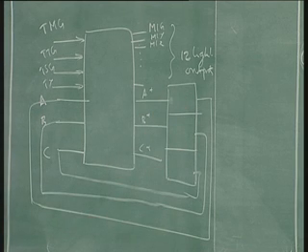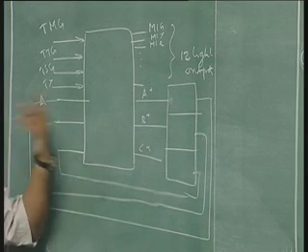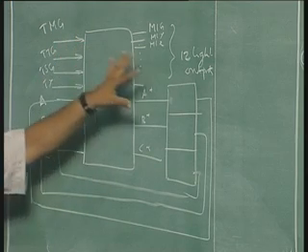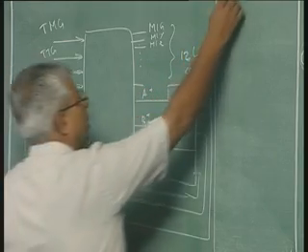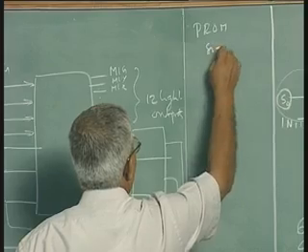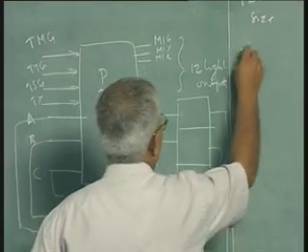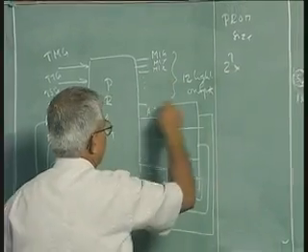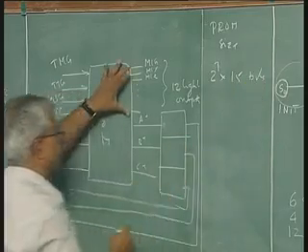I can implement it using flip flops and combinational logic. This combinational logic can be gates, multiplexers, PROMs, or you can put the whole thing in a PAL, programmable array logic. If it's a PROM solution, the size would be 2 power 7, 12 plus 3. I am assuming no reduction in the signals.